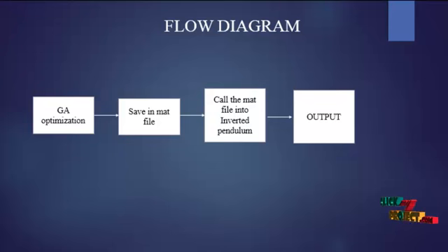It is also required to hold the cart at a reference point on the rail. Once the pendulum is stabilized, a transition algorithm switches smoothly from one control phase to the other. This technique aims at swinging up the pendulum while keeping the cart within a limited horizontal travel on the rail. This is actuated by satisfying particular mathematical conditions derived from the mechanical energy equations of the pendulum.